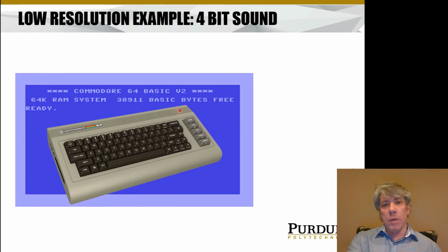But in this computer, of course, one of the things you needed to have a decent video game is some sound, right? So this computer had what was called a SID chip, SID, a sound interface device, I think. It was basically just a little synthesizer that had 3 voices, and you could make a square wave, triangle wave, or noise, I think, or a sine wave, and make different bleeps and blops and things. Think old school video games with very crude sound.